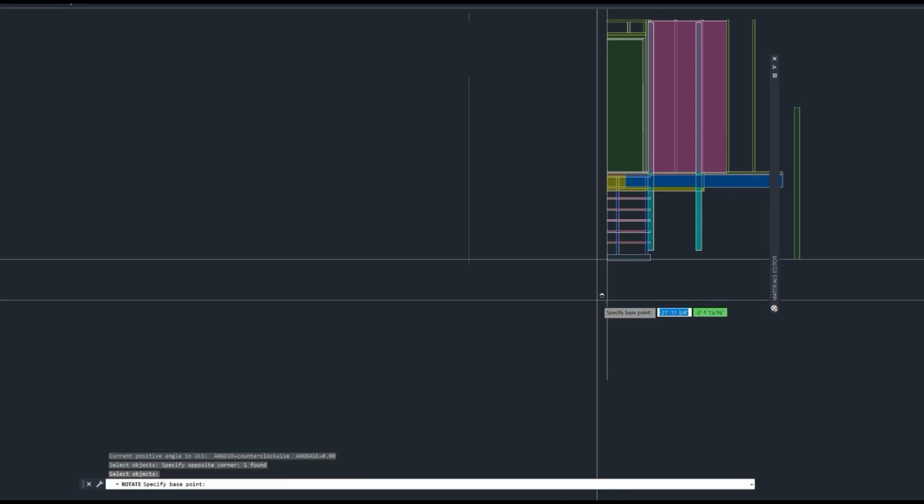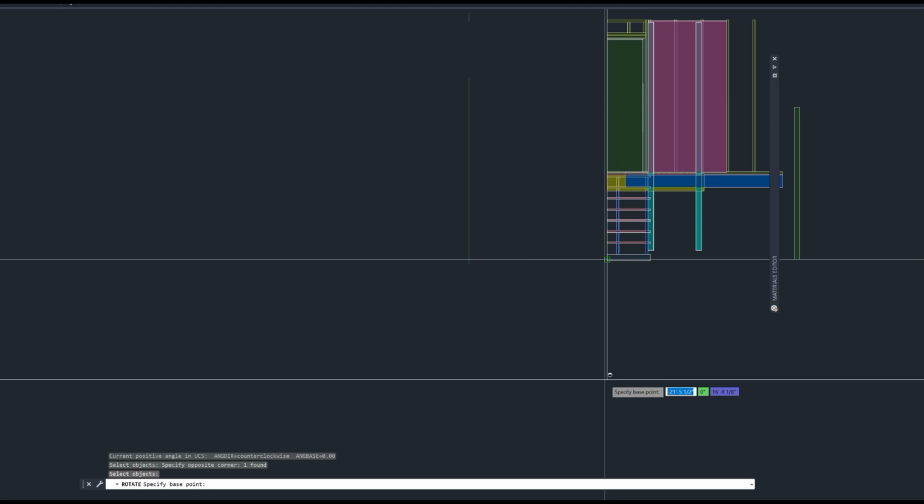Go to a plan view, select the plane and rotate the section plane as required. Notice the slice is precise at an angle, which may be helpful for some 3D objects depending on the detail of your models, but it works quite well.